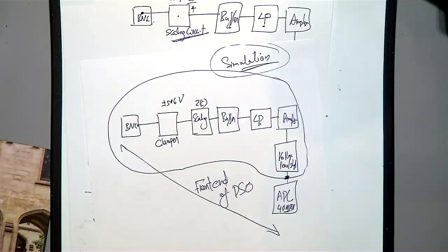Why don't you put gain in the filter? There are so many ways you can do it. If you introduce gain in the filter, then you may not need the amplifier. But you may need an inverting amplifier if your filter is an inverting filter. If your filter is inverting the signal, then you have to invert it back. You know what I mean? Then you need an inverting amplifier. So this is one way of implementing, but you can implement that block in a different way.